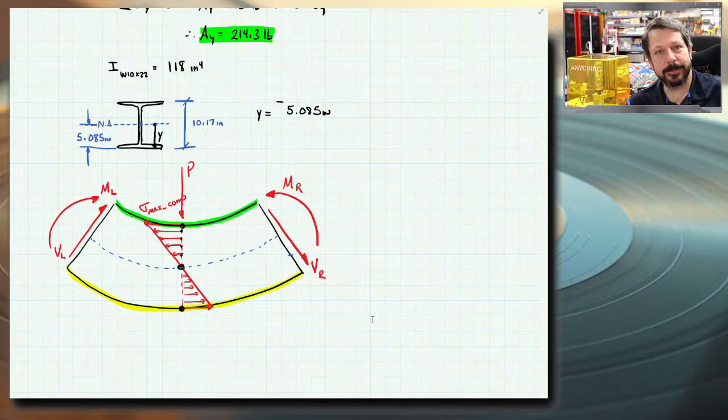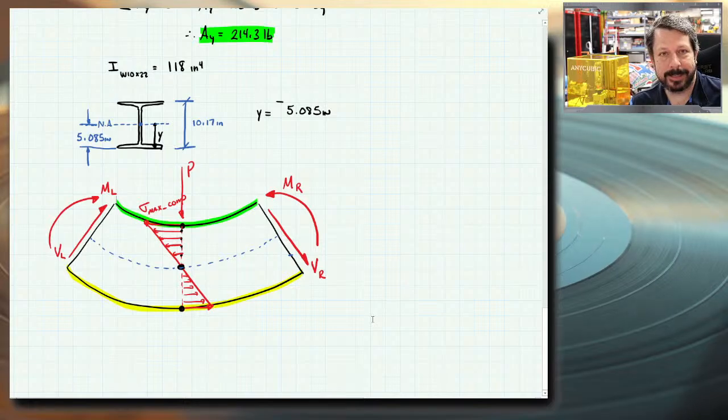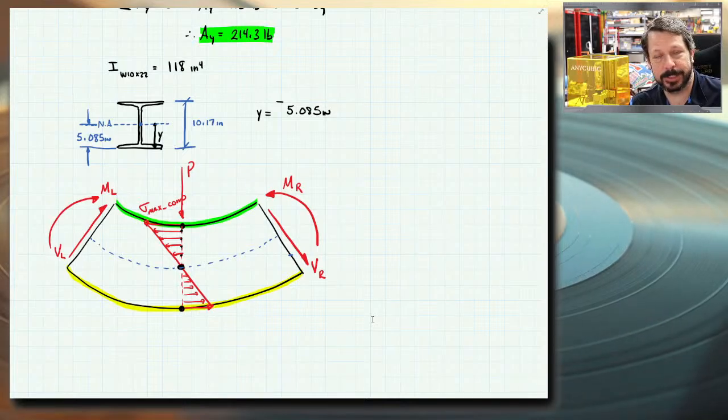Most of the time I'd tell you can choose whatever orientation you want, as far as left being positive or negative, up being positive or negative. You can choose all of that. This one thing we have to agree upon so that our stresses end up the same. Otherwise, if you assign a positive bending moment where I've assigned a negative bending moment, or vice versa, then we'll get the same magnitude, but not the same value.